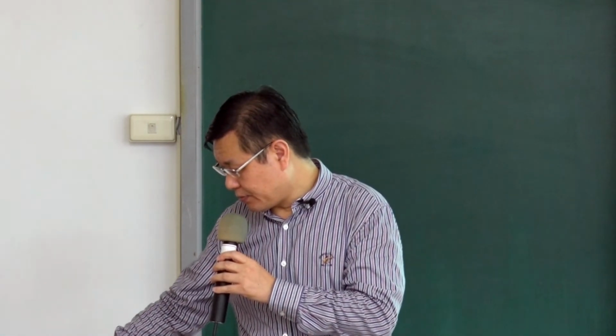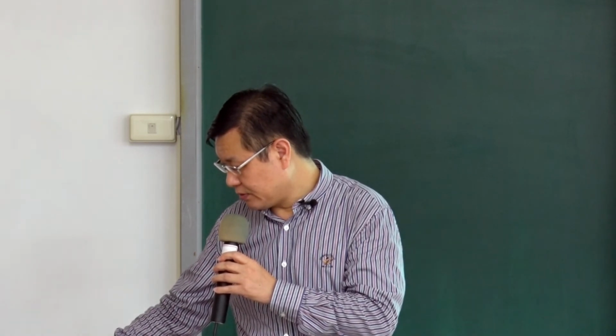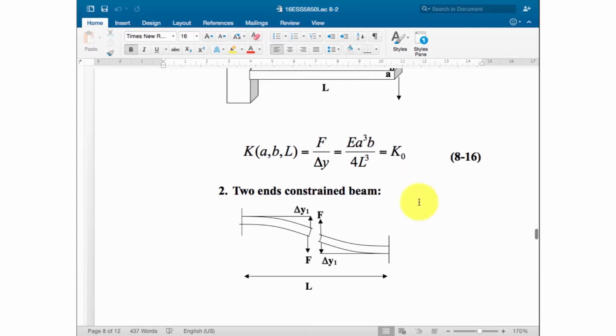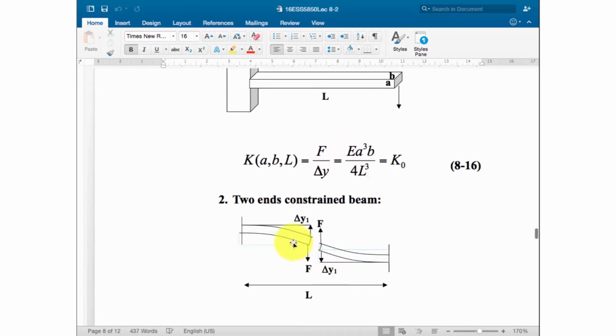So now we consider the original length L gives you this kind of spring constant. For this new type of spring, what kind of spring constant will it have? So we consider back this equation. For this kind of spring, you have two similar springs connected in series. Each spring, the length will be L over 2, half of the length.